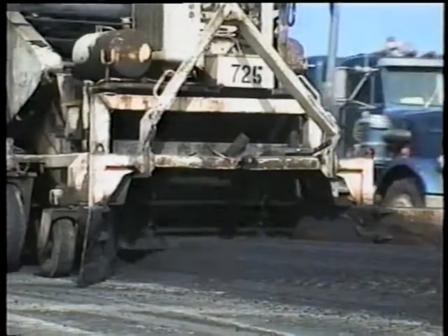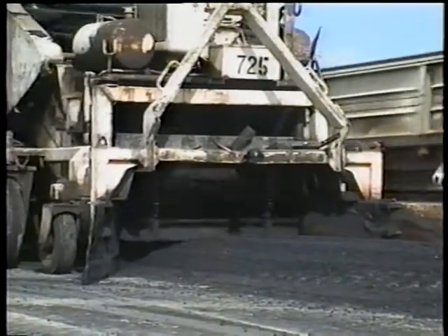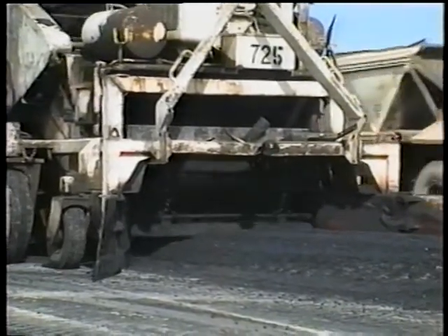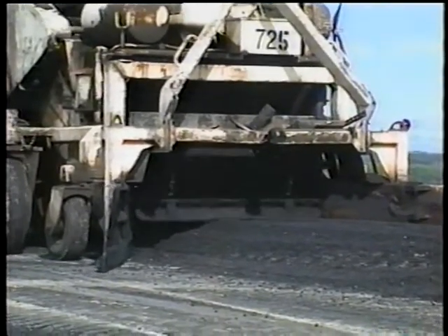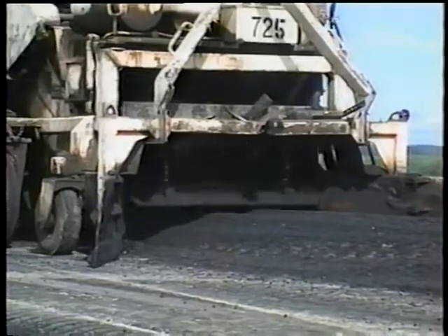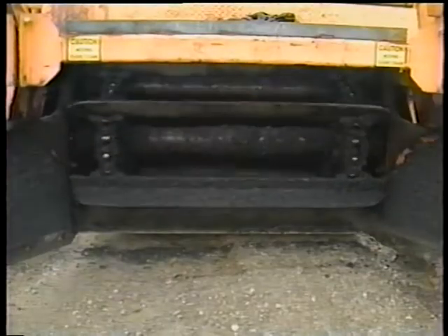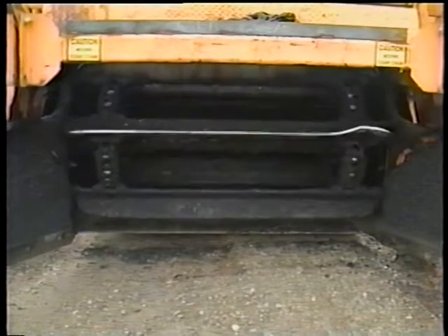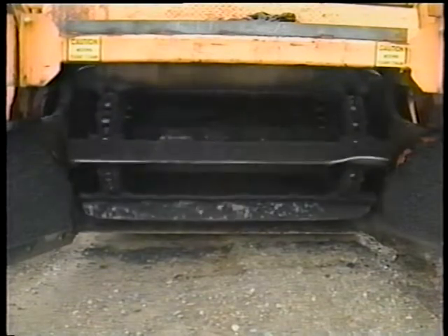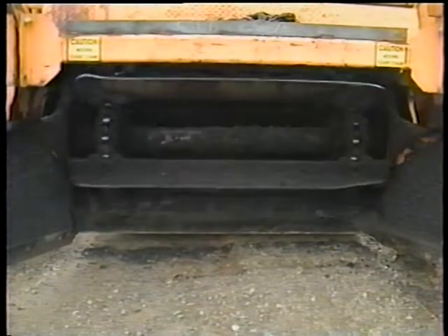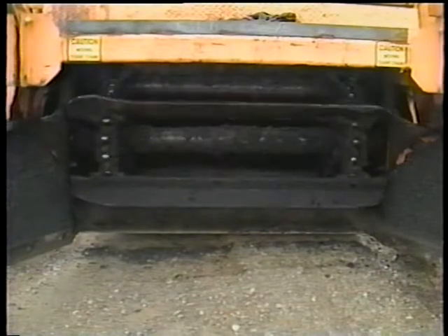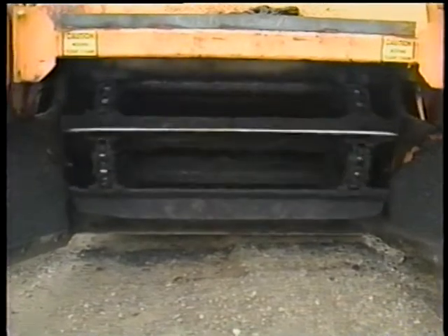When belly dump trucks are used, a pickup machine is attached to the front of the tractor. Let's take a closer look at each component, beginning with the pickup machine. As you can see, it's pretty basic. The wings on each side of the machine are used to channel the mix toward the paddles, which in turn load the hopper. A plate is mounted below the paddles to ensure that all the mix is picked up.